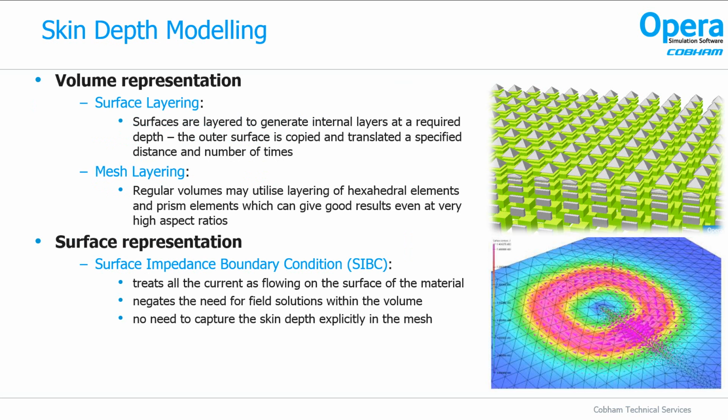Another practical consideration when performing finite element analysis of eddy current NDT problems is skin depth modelling. It may be impractical, resource-wise, to mesh a whole problem with finite elements discretized to the size of the skin depth of the problem, so users need a way to accurately perform calculations at the surface, but utilize a coarser representation where the numerical integration points are unnecessary.